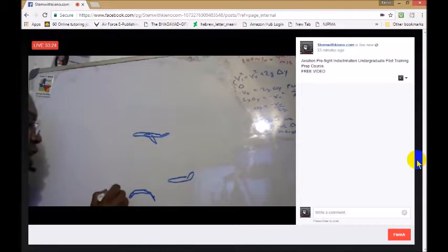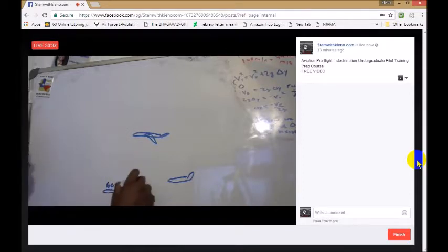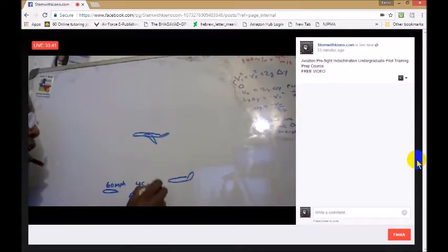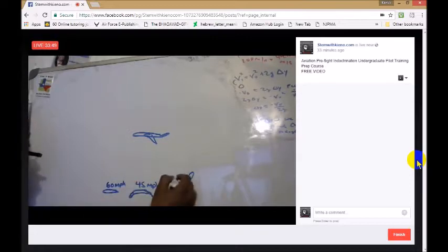So if the airfoil just looked like this, we would need at least 60 knots or miles per hour. I'll keep this in layman's terms. But with the flaps and the slats extended, we could slow down to probably 45 miles per hour. This is why when you look out the window, you'll see the slots or slats or different panels sliding down and curving, because we're in a landing configuration.